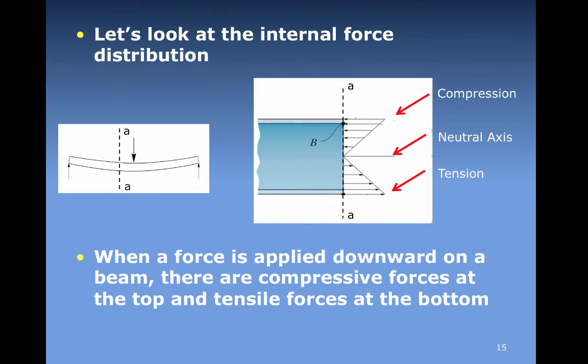If we now take a cross-section of the beam and study how the stresses appear, I want to remind you that the neutral axis is an axis where there is no extension or compression. Therefore, there is no strain. As we've talked about already in three-point bending, we find that there are compressive strains above the neutral axis and tensile strains below the neutral axis. Therefore, through Hooke's law, we know that there will be compressive and tensile stresses above and below the neutral axis. But it's important to note here that these are linearly varying stresses because the strains are linearly varying.